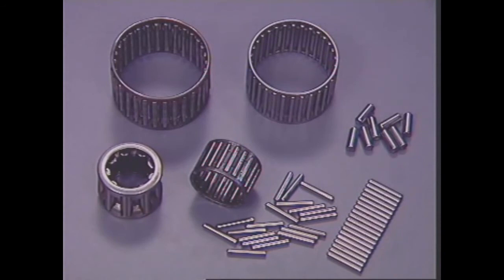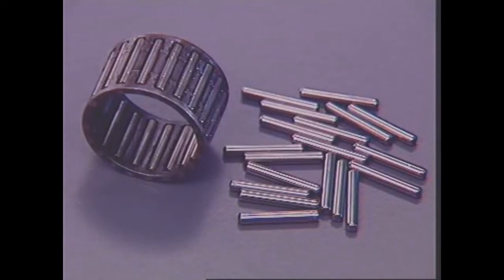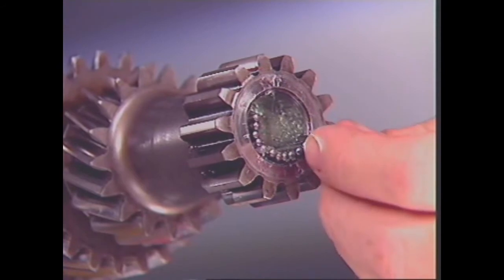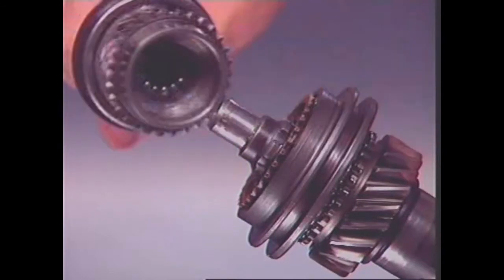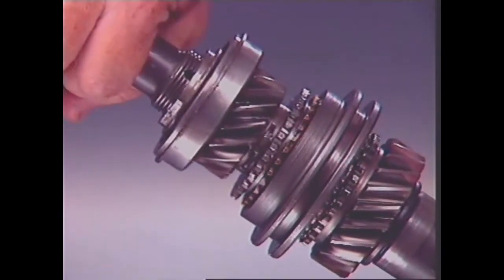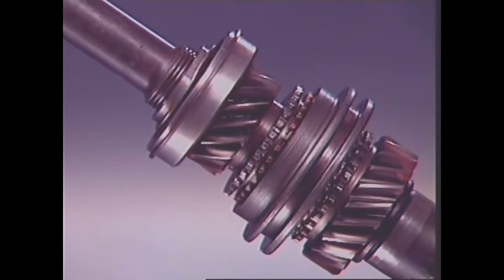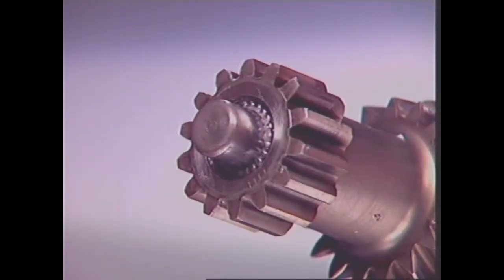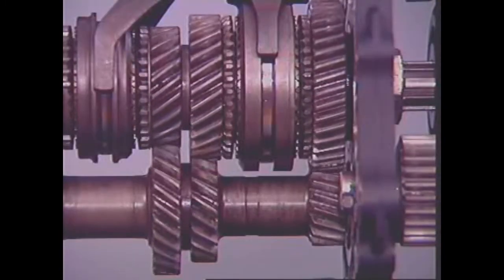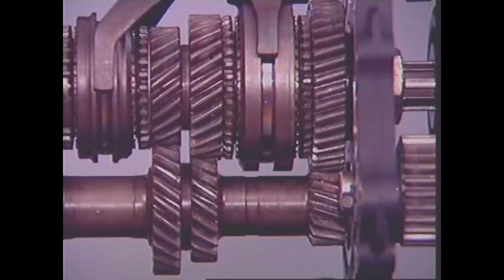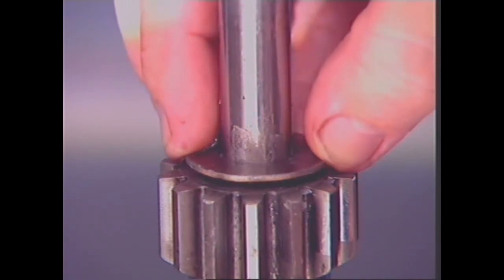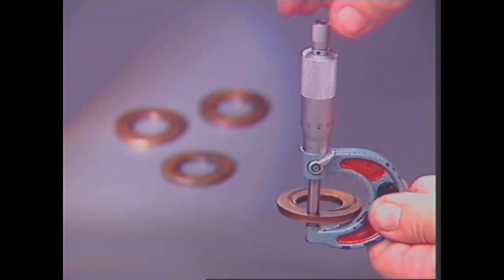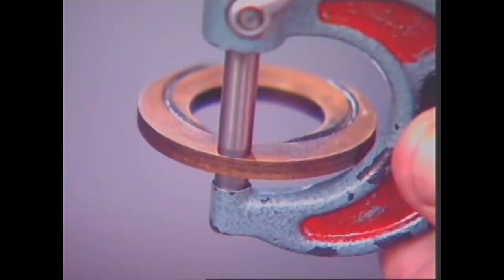Roller bearings are common where loads are purely radial. Needle roller bearings can be caged or as a loose number, assembled to operate directly on a hardened gear or shaft. Typical applications are the spigot on the front of the main shaft, supported in the rear of the input shaft, and in some cases on the counter shaft, and the freely rotating gears on the main shaft. Separate thrust washers can retain them and cater for thrust loads. They are often a selective thickness to allow for end float adjustment.